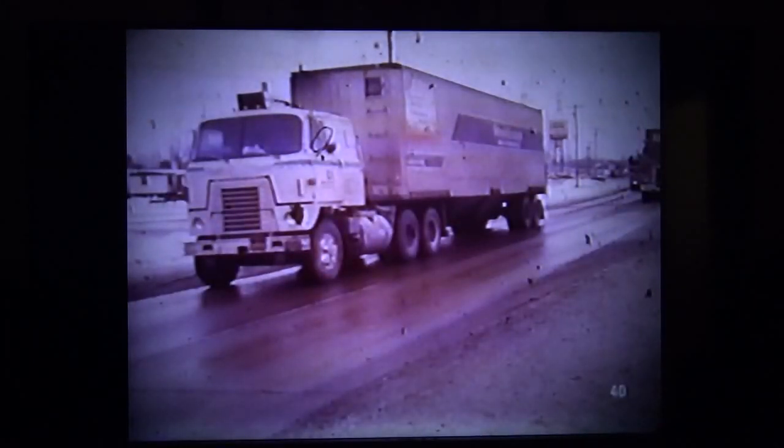It's important that road testing be done under actual operating conditions. Often a load or type of load, trailer or type of trailer will influence a disturbance. For this reason, don't bypass this very important step, even though it may be inconvenient. While out on the road, test the vehicle in a combination of transmission, auxiliary transmission, and multi-range rear axle speeds.